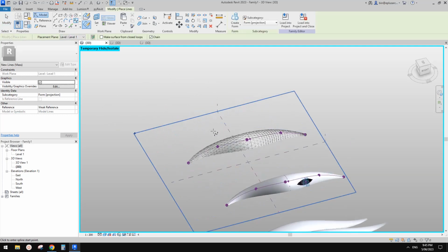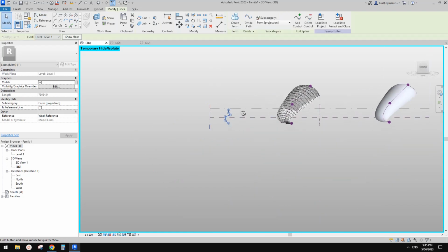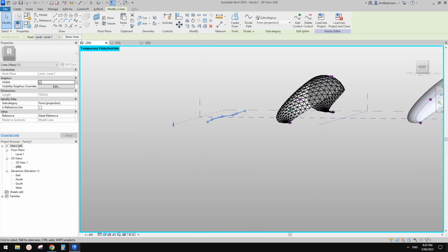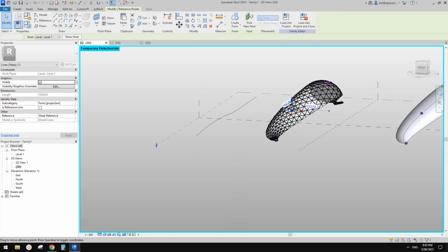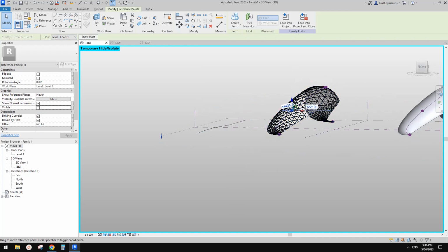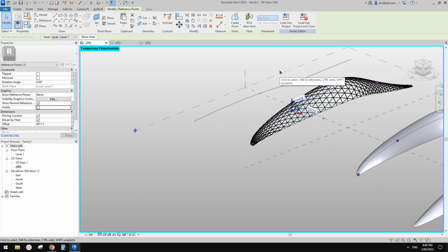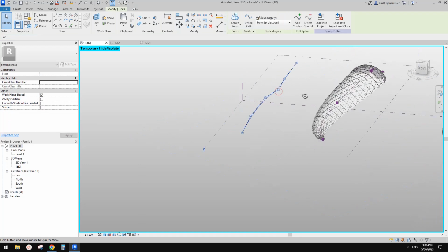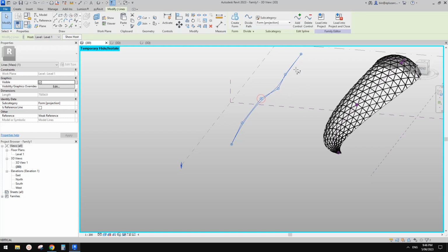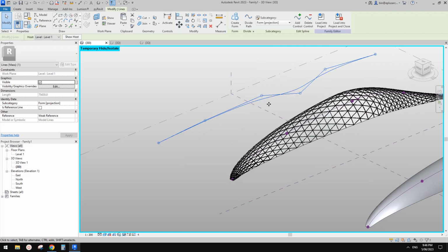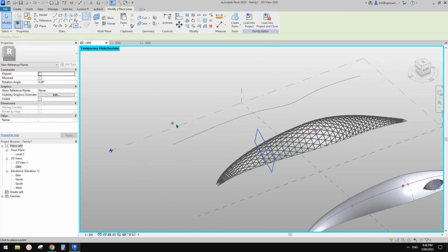Okay, spline. So spline is a curved line that can only be 2D. So it can only be placed onto a surface. You can only move the points in the 2-dimensional plane, not three dimensionally. But you can still place a point onto this spline, use draw on face onto this spline.